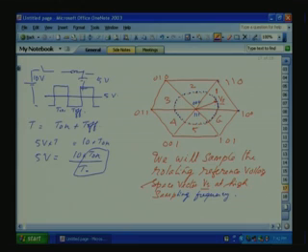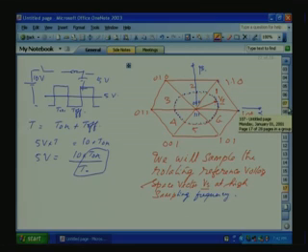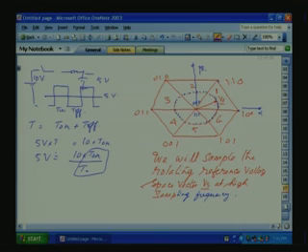So we have to take the volt second along the alpha axis and the beta axis, the orthogonal axes. So the component of Vs along the alpha beta axes, in volt second: Vs for the sampling period Ts, the component of Vs along alpha beta multiplied by the sampling period, that is the volt second of the reference voltage along alpha beta. It should be equal to the volt second of the 1 0 0, 1 1 0 and the 0 vector along alpha beta. So if the volt second is matching, by switching, the average variation of Vs is generated.